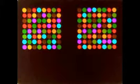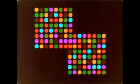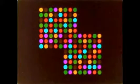Now, any two neighboring elements will have nodes in common, so values for common nodes will appear in both matrices. The matrices can therefore be combined by a simple merging technique. In practice, the process of solving the overall system equation is done concurrently with the combining of the matrices. The whole process is known as reduction.